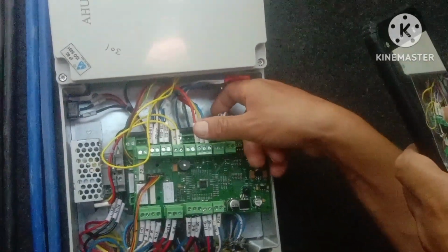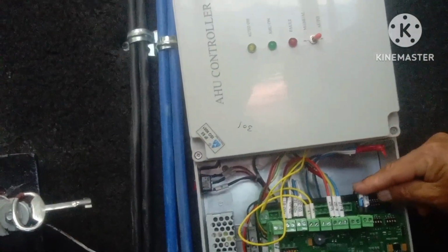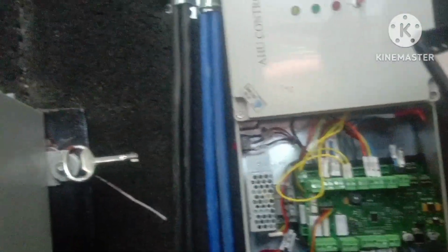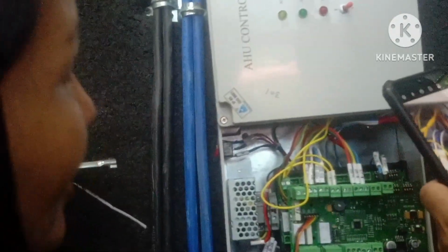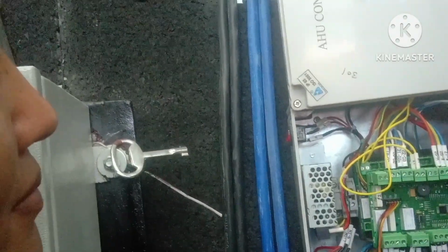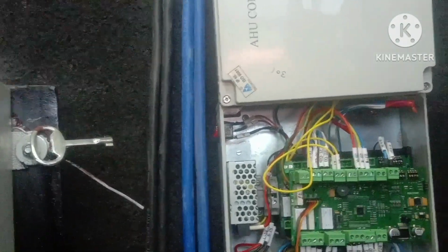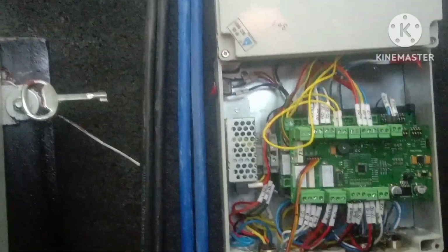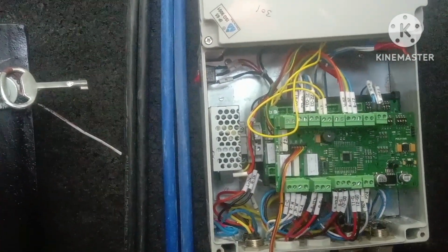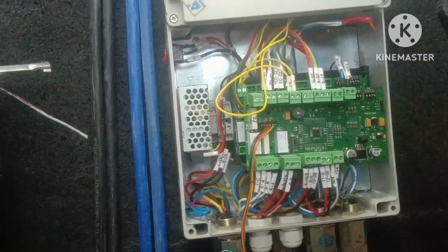If I remove that wire, I will see the hash or hazard sign, which we are seeing on the 4th floor on one of the cassette units. That means that wire is not connected properly or that Modbus unit is not working. I told you, we are communicating with all devices on one communication protocol, that is Modbus RS485, which is connected here.